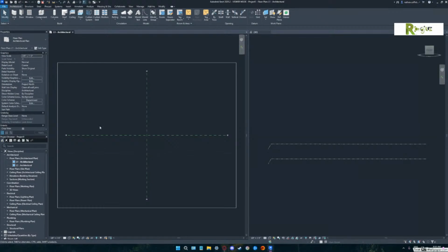I want you to look at the top of the properties box. Look at that. Click on that and hit the arrow. You would see that you can change it back to, and let's change it to 1/4 inch since we're going to be doing a small building. That effect doesn't happen until your mouse comes off the properties box.